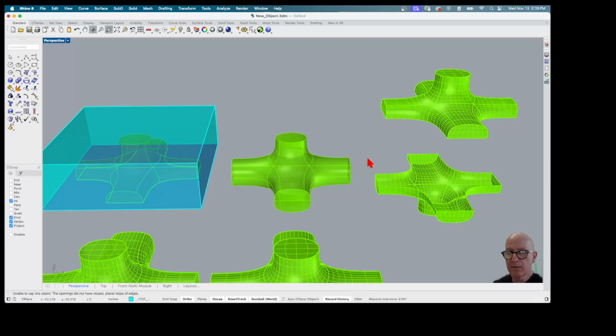So the next thing we're going to do is a procedure to generate that top surface so we can create a solid NURBS object now that we don't have SUBDs anymore, because you've reached your final form and you're ready to use it in a subtractive manner to develop your mold. So let's have a look at how to do that.